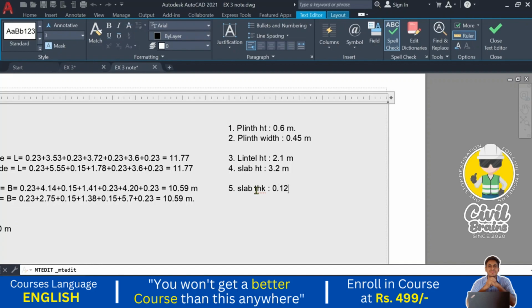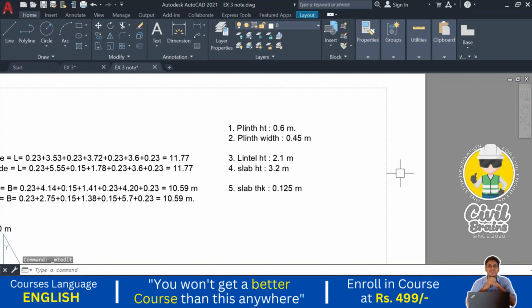Because in most residential buildings we consider the slab thickness as 0.125 meter as per structural safety. If it is a commercial or any other public building, in that case we consider the slab thickness as 0.15 or more, depending upon the structural design.